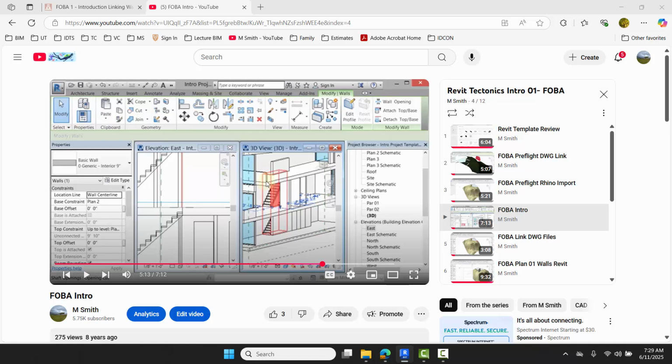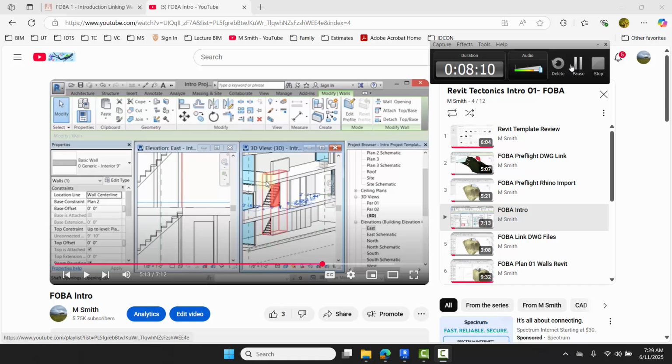There's also a thing called a mark. So I could name this W9-1, right? And then this one still does not have a mark because it's an instance parameter. They can have unique marks, and there are reasons for that. So I can name this one W9-2, right? And so this one is W9-1. This one's W9-2. So I hope that starts to make some sense in terms of what an instance and a type parameter is and what we're going to be working on.